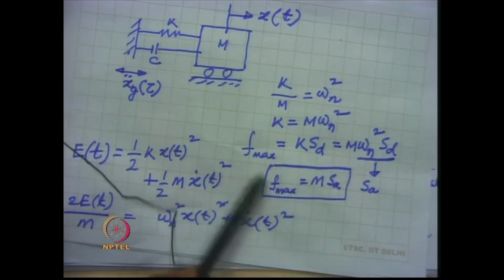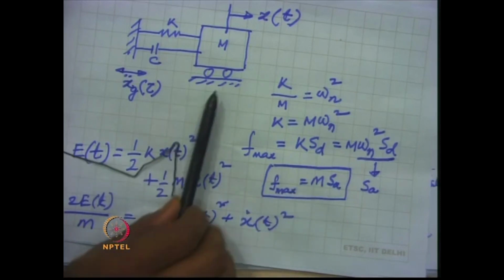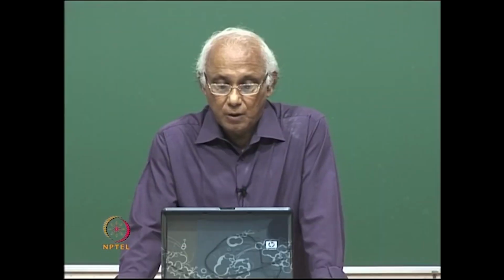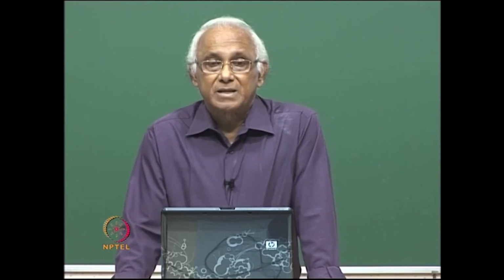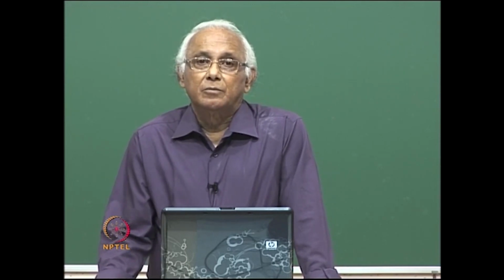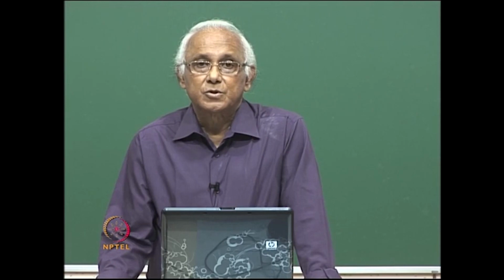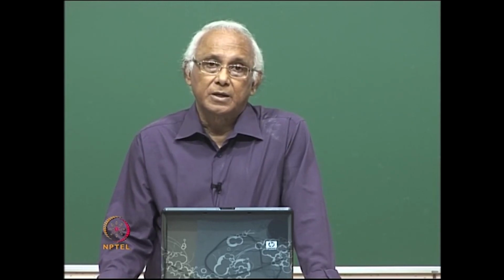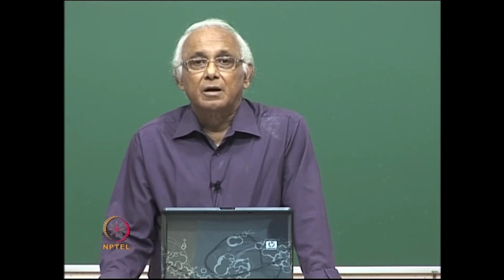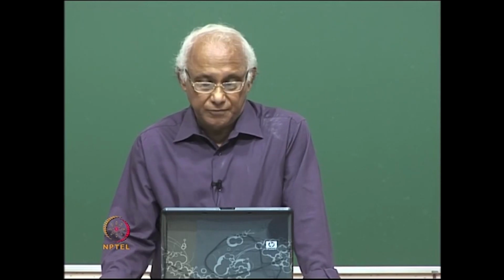So, therefore, F max becomes equal to mass times the spectral acceleration. Now, that is a very interesting thing, and the spectral acceleration therefore becomes a very useful quantity for defining the maximum force in the structure. What we need to know for finding the maximum force in the structure developed due to earthquake is the mass of the structure, which is easier to obtain than the stiffness.